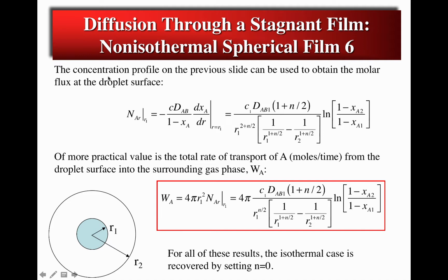Typically what we're going to want is to use that concentration profile not as an end in itself, but as a means to calculate the flux. And now we'll calculate the flux at the sphere surface using our flux expression. Now with the concentration profile, we can evaluate this derivative. The result is given here.